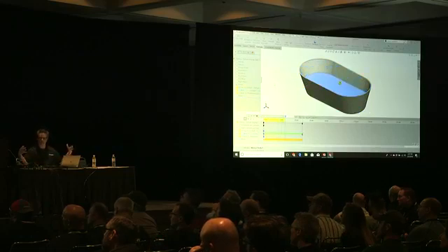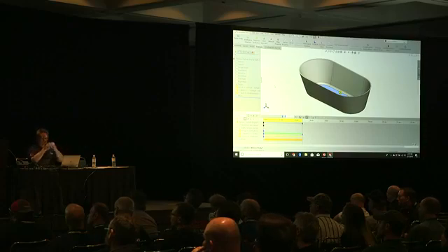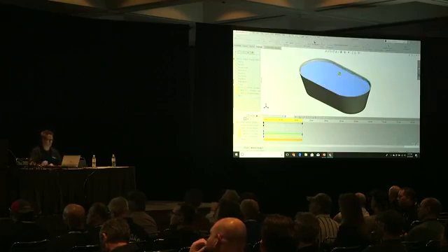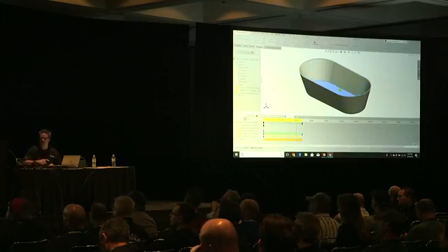The way the water's set up, I did a square solid, and then I did a 0 offset surface on the inside of the tub, subtracted that out, so that's all that's left. So as that moves down, it stays with that surface. And so now I can play a draining tub. The duct came from 3D Content Central.